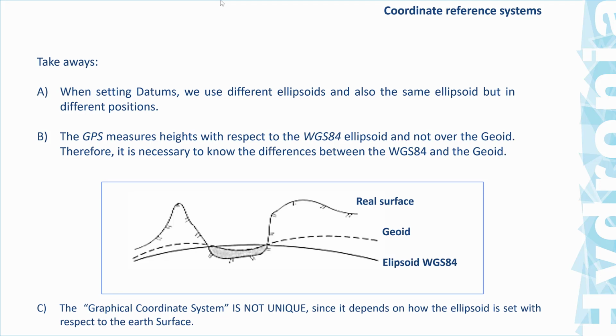And the point here is that you need to understand that this is different in general from the datum that you would get from a geoid, that is a different surface. So it's a kind of confusing, but I think the graph here explains it in a better way. So this is a cut on the surface of the Earth, and you have here the ellipsoid that is a mathematical representation of the Earth's surface.